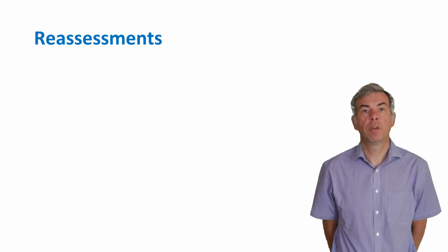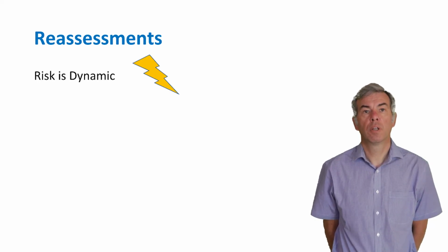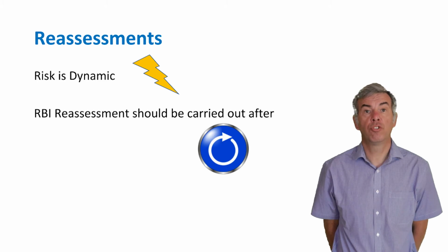The final step is the reassessment step. Risk is dynamic. It changes with time. And results from an RBI assessment need to be updated by qualified personnel. An RBI reassessment should be carried out whenever changes occur.